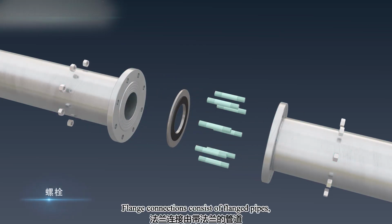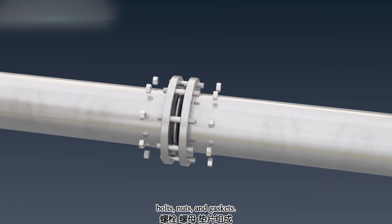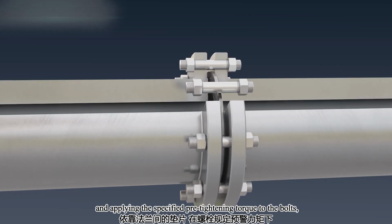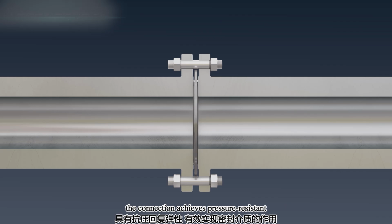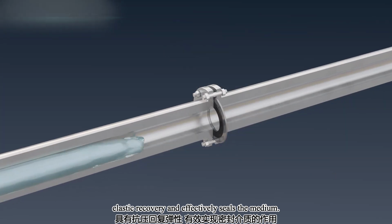Flange connections consist of flanged pipes, bolts, nuts, and gaskets. By relying on the gasket between the flanges and applying the specified pre-tightening torque to the bolts, the connection achieves pressure-resistant elastic recovery and effectively seals the medium.